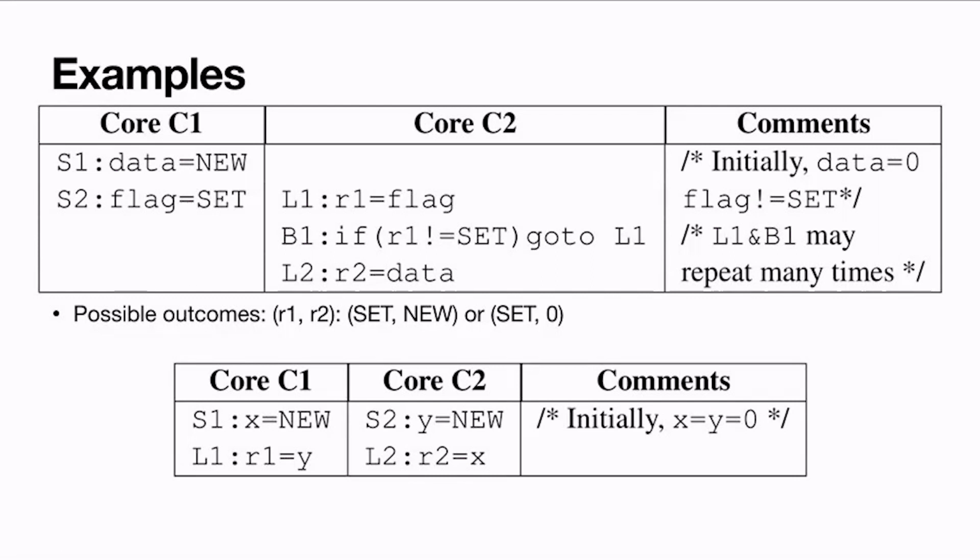Right, but the thing is, you're not just waiting for the store to be committed, right? That's the whole point we discussed in the morning also, because stores are not critical. We just write it to the store buffer and say, from the system point of view, okay, the store is done. But we'll be writing that later.